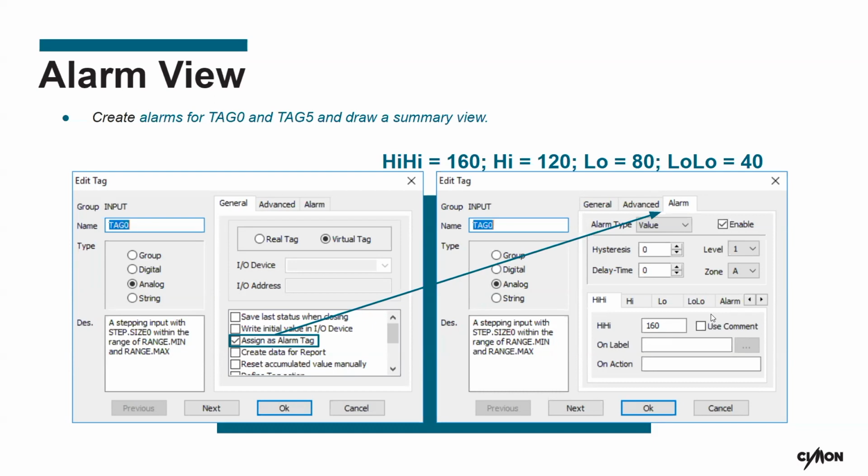So you would want to be notified when you pass 90% because you need to intervene immediately. That means the drain system is not working accordingly, or the pumps are working too hard, not turning off when you tell them to turn off, something of that nature. There needs to be an emergency contingency for when you reach certain thresholds. Likewise, on the low side, if you're below 10%, that might be a cause for concern. Maybe the pumps aren't working and water is not being delivered to whatever locations need it. Not as big of a concern as high, because something could be destroyed, but with low, water is just not getting to where it needs to get.